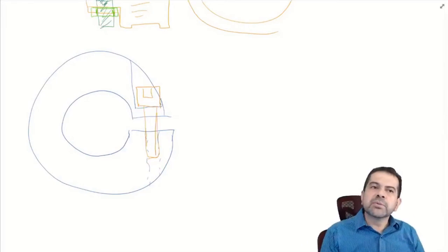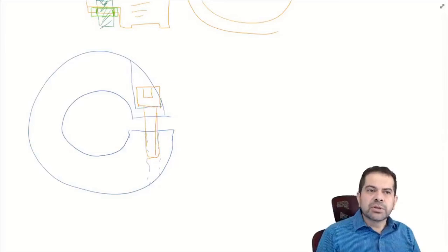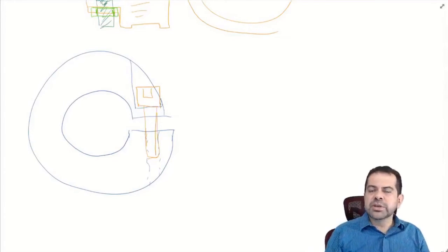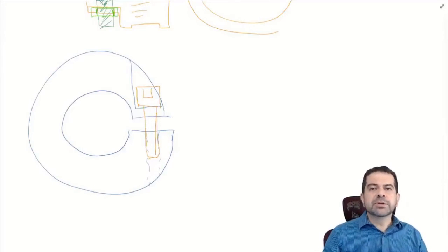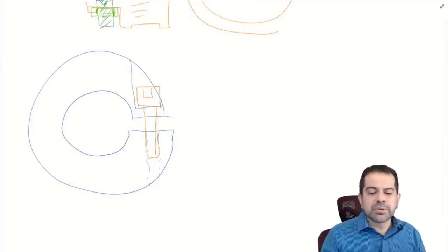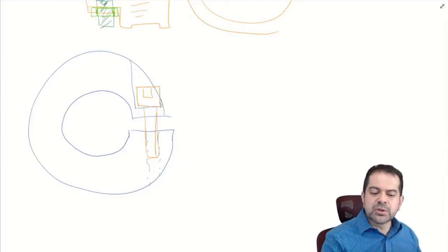Now, you will see different approaches, and whenever possible, keep this in mind. You should try to find out what exists already, what standard components are available. Standard meaning off the shelf. It's ready to go. I just buy it. It arrives 2 days later, rather than designing your own thing. Design for a component that already exists. Purchasing such a component compared to the amount of time you're going to take designing it, doing the engineering drawings, getting it fabricated and all that, there's no question. It's much better to go with standard components. But there are times when you need to custom design something.